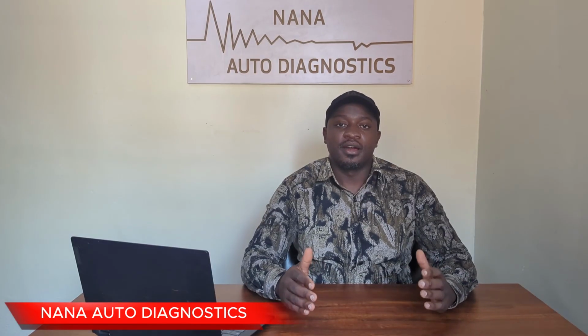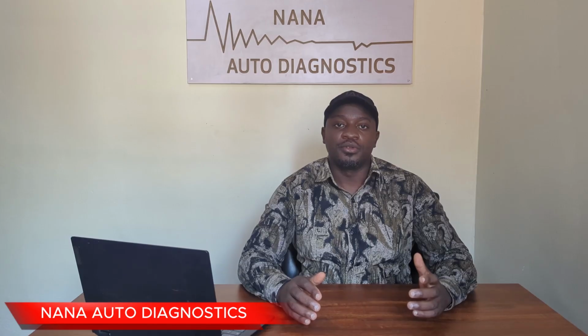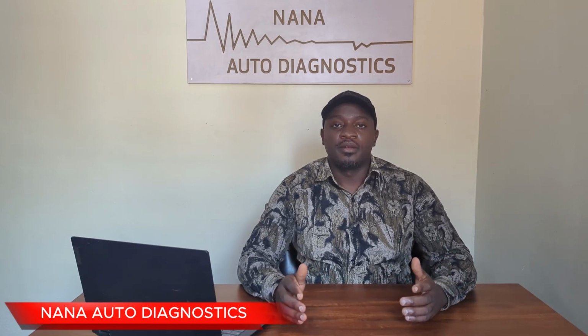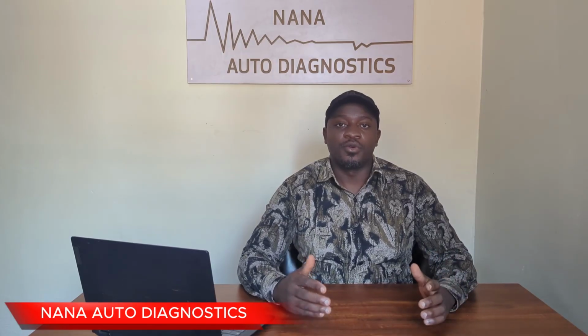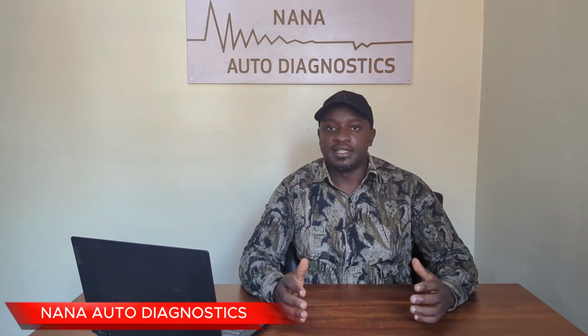According to this master-slave architecture, the commander ECU, we can call it the master ECU, can connect up to 15 slaves or slave nodes on any given network. For instance, the body control module, sometimes known as the BCM, can control the central lock, wipers and washers, windows and other body and comfort related systems.